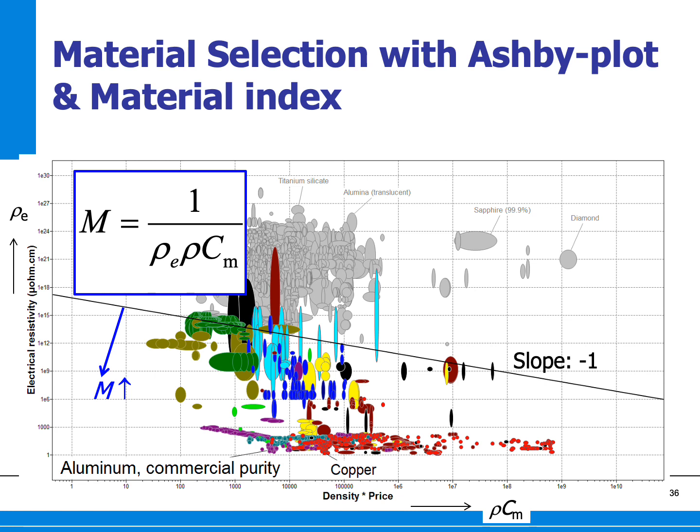So if we do so, we will find that aluminum is in fact the best choice for this problem. So aluminum has the lowest cost while still fulfilling our boundary condition that the resistance of the cable should be below our R max. So that's a nice and maybe slightly counterintuitive outcome of this analysis.